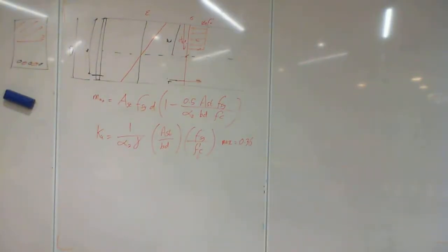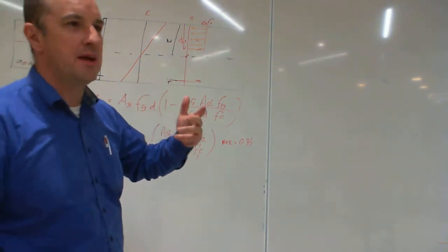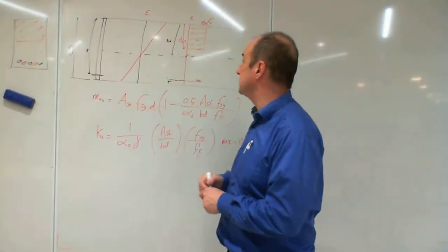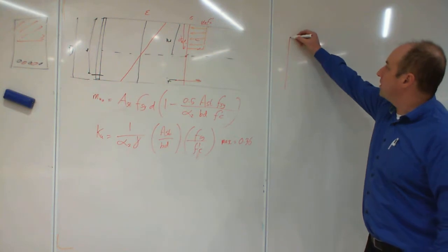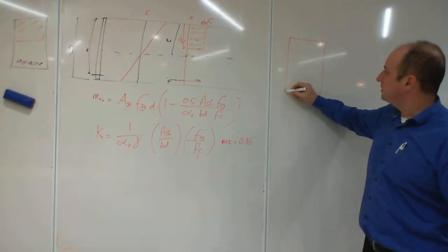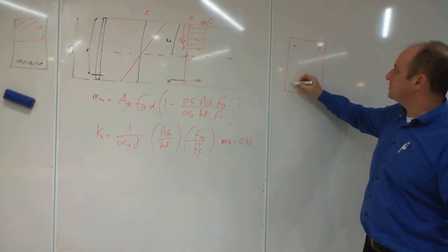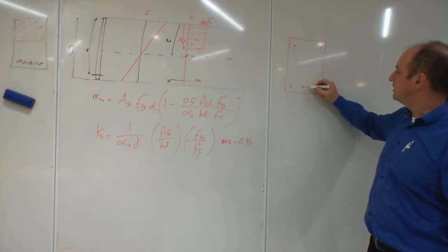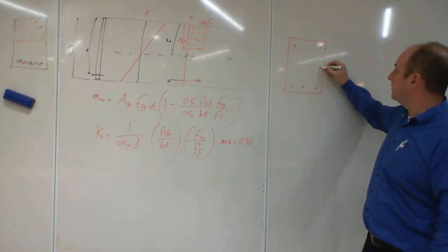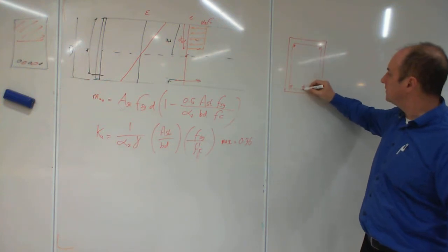Okay. The vast majority of concrete beams, when you design them, are designed as singly reinforced concrete. But when you go on site and you look at concrete beams, you will find they always, or almost always, have top steel in like that, and then the rings around that go like that. Okay?